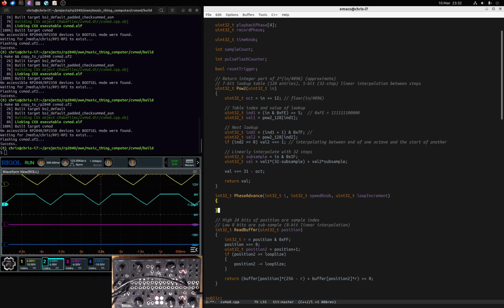So the trick with how unsigned integers are actually integers modulus 2 to the 32 in this case, in principle doesn't always work with signed integers such as this integer, but on the RP2040 it does work, and so you can treat them slightly interchangeably. We don't need to worry, on the RP2040 and with this compiler, about the fact that overrunning the end of a 32-bit integer is undefined behavior. That just works. So what do we actually want to do?